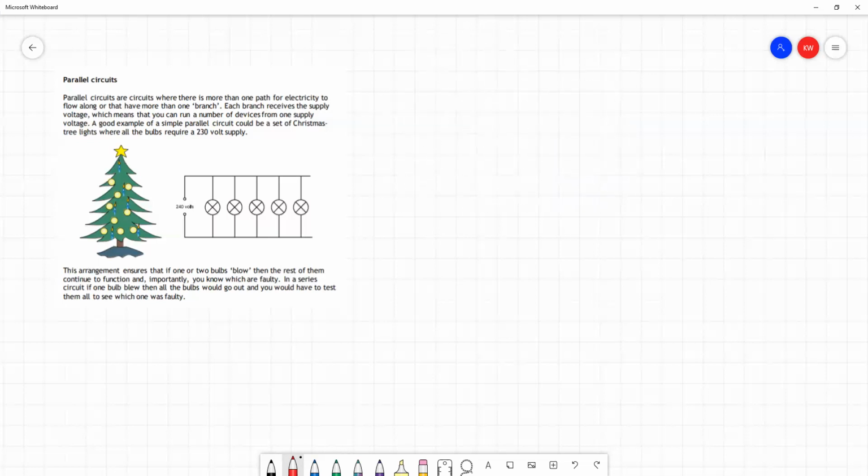That would also mean that if we found some way to bypass it, which of course does exist within bulbs, where we can have bulbs that go out but still allow current to flow, the voltage would change as well, because the voltage has to add up across all the components to the total circuit voltage. So, a couple of disadvantages to a series circuit.